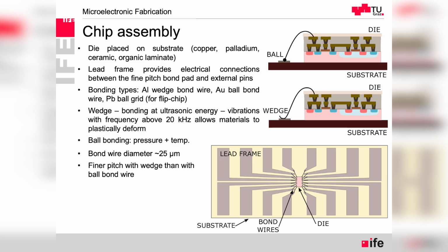The difference in the bonding is also which one has a finer pitch. So scaled technologies will have smaller and smaller bonding pads, and also they will be closer together so that, for scaling, we can add many more control interface signals. Because of that, very often we need to have fine pitch, and then wedge bonding will be better.